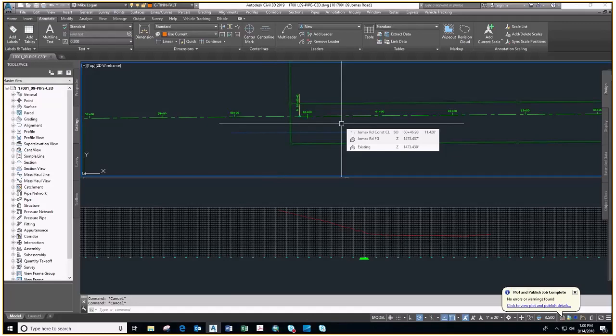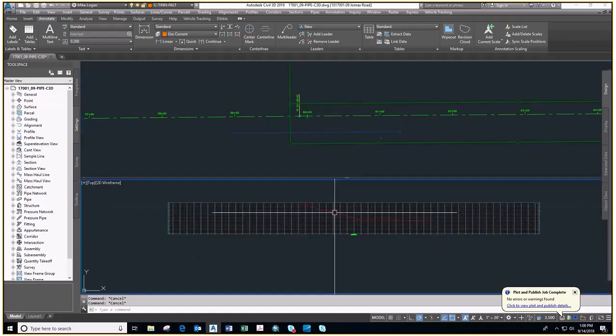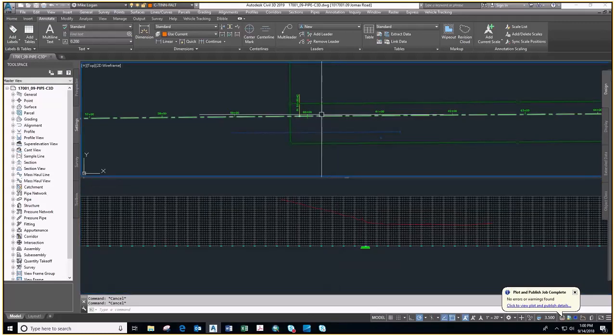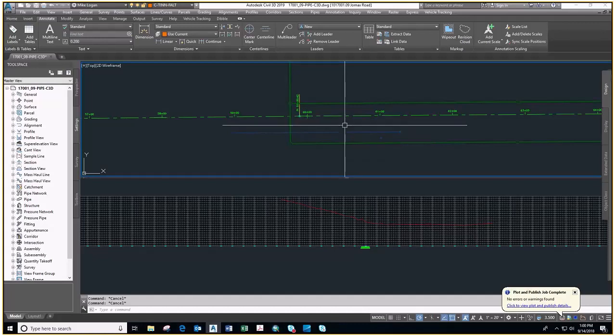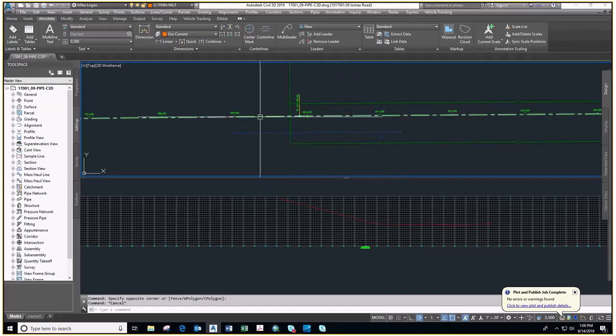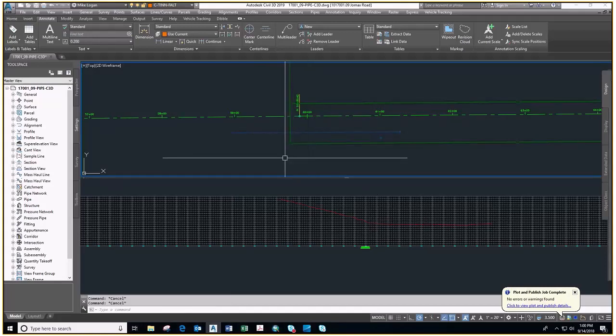There's also a profile view and a surface profile cut along the alignment. This is the roadway construction alignment. This is usually along a section line, and it's usually not right on top of your pipe. If you notice in our construction plans, we show centerline stationing, but our surface profile is always right on top of the pipe. And so I'll show you what that does.